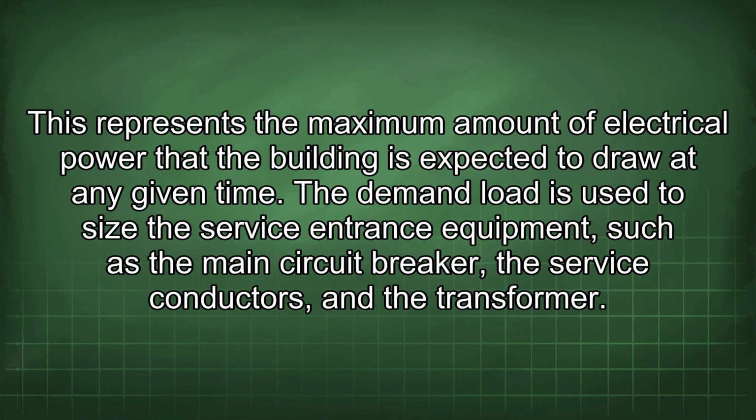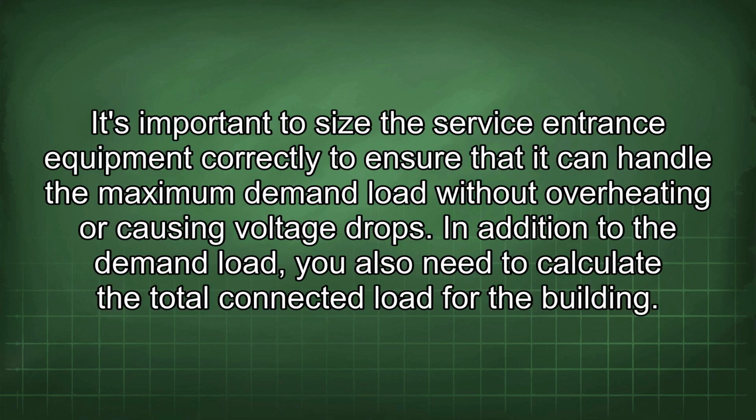This represents the maximum amount of electrical power that the building is expected to draw at any given time. The demand load is used to size the service entrance equipment, such as the main circuit breaker, the service conductors, and the transformer. It's important to size the service entrance equipment correctly to ensure that it can handle the maximum demand load without overheating or causing voltage drops.